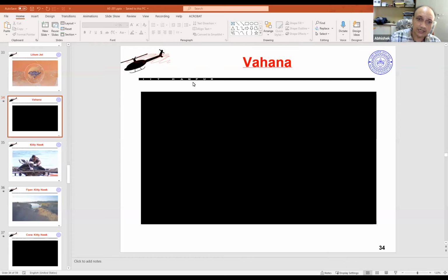Now, once the agent which is causing this adverse pressure gradient or jump in pressure which causes the separation is removed, the flow may reattach. Normally, when I reduce my angle of attack, the adverse gradient goes away and the flow will reattach. And if my airfoil is undergoing dynamic motion, like the way it happens in helicopter rotor blades, this dynamic motion can cause reattachment and separation multiple times. So your flow may separate, it will reattach, it will separate again, because the flow is dynamically oscillating or moving up and down and doing all kinds of things.